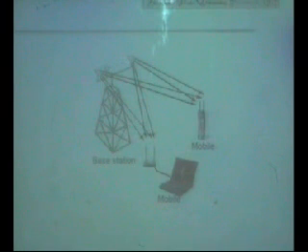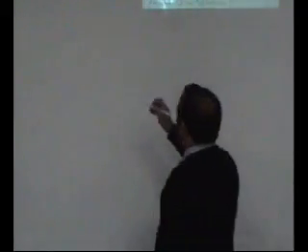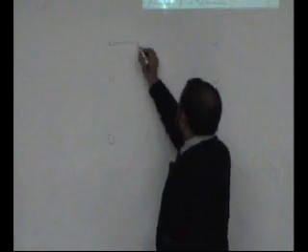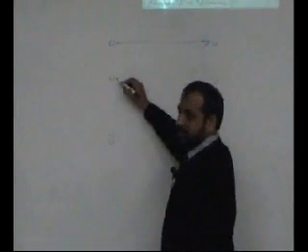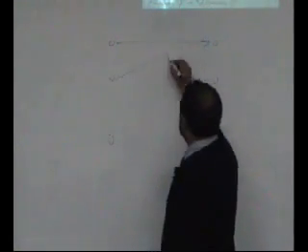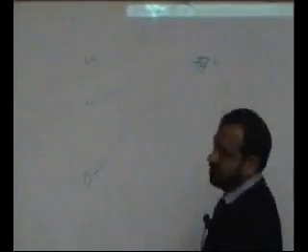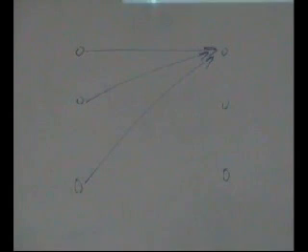So if you have 1, 2, 3 transmitting antennas and 1, 2, 3 receiving antennas, how many channels do you need to worry about? Nine. Because this antenna's signal comes here, that is 1, and the signal this other antenna transmits also comes here, and the signal this transmitter transmits also comes to this antenna. So 3 for every antenna.